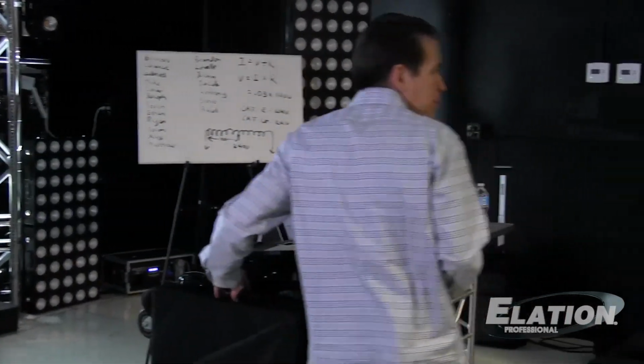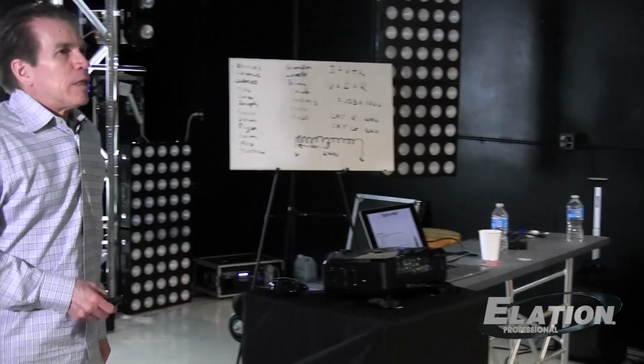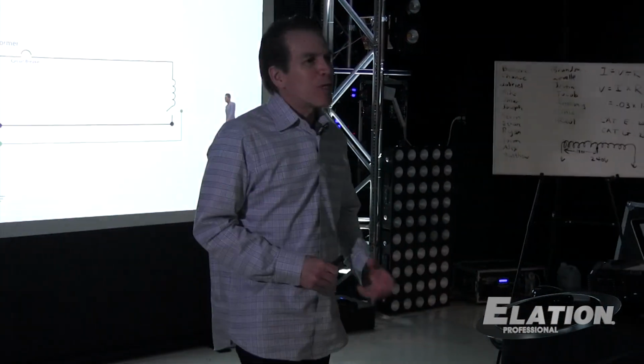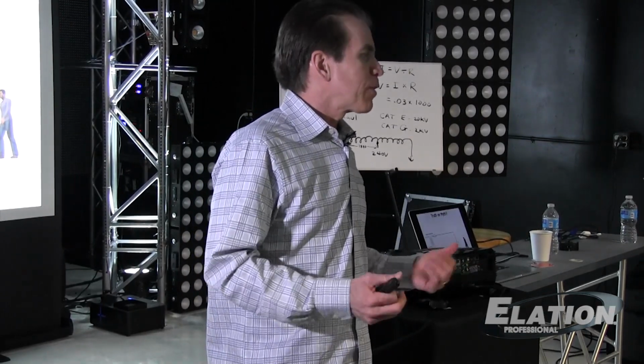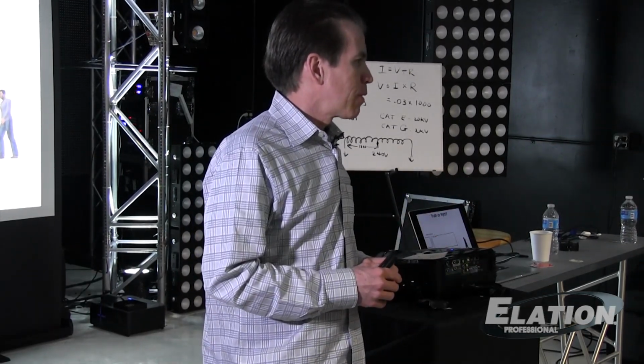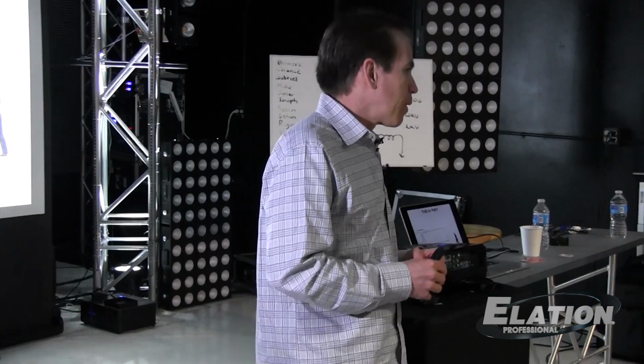How's that measurement called? What's it called? Yeah. So what's the measurement called? I just call it measuring the voltage between the neutral and the ground. I don't know that there's any special term for it. Well, what kind of problems will you find on site if you reach, say, 5 to 7 volts?